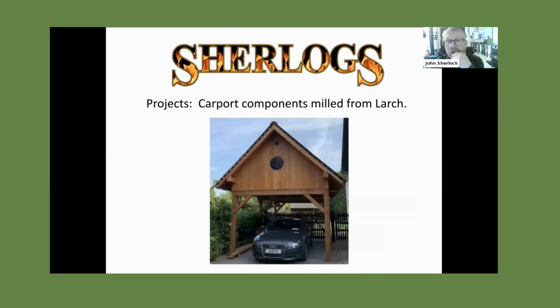So there's an example now of Irish grown timber that we made into a carport. The posts there are 150 by 150 section, so you'd possibly get that out of a 200 or less circular tree. And that's what I'm saying. I loved Dr. Ian's presentation about the value of timber, that in the first 6 meters there's 80% of the value of the timber, and that would be for quality sawlog. But if we look beyond that, post and beam timber would be a lower grade timber.